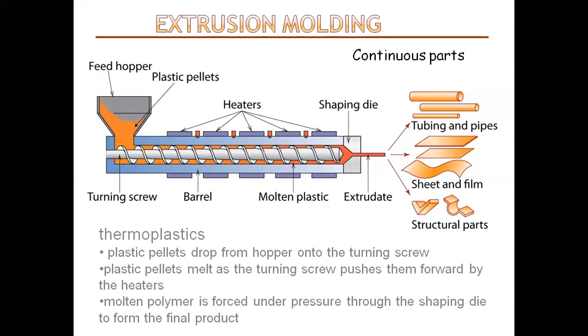molten plastic, which is in the range of 200 degrees Celsius to 275 degrees Celsius, but it normally depends on the polymer. Okay, so this is what happens in extrusion molding. In most processes, a heating profile is set for the barrel, in which three or more independent PID control heater zones gradually increase the temperature of the barrel.